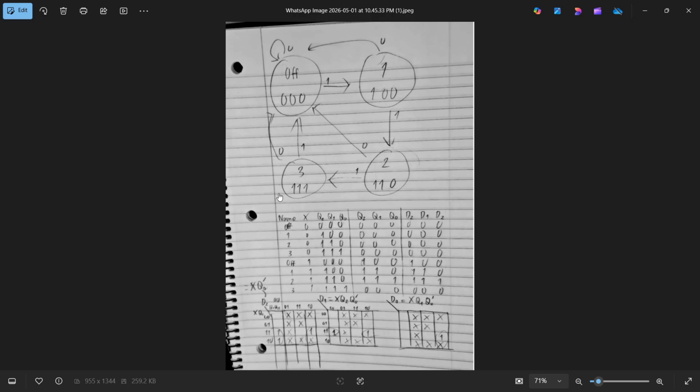The logic gates implement the equations I derived earlier. The clock controls the state transitions. When x is 0, all lights are off, and when x is 1, the system starts cycling through the states. You can see the sequence 000, 100, then 110, and then 111, and then it repeats. For that I have used 3 D flip-flops, AND gates, clock signals, an input switch, and LED outputs.